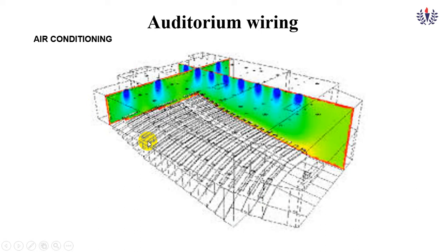Here you can see the air conditioning. So this is very, very important, because in whatever type of auditorium, there will be the ducts for circulating the AC. So there are two types of AC. One is the window AC, the second is the centralized AC. So this is actually a centralized AC where the AC unit is placed somewhere out of the room, but through ducts, the conditioned air is equally circulated. So this is also very, very important. Based on this, we have to locate the places, and that is in between the center according to the plan of an auditorium.